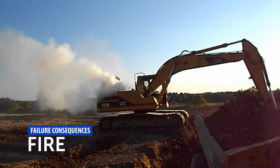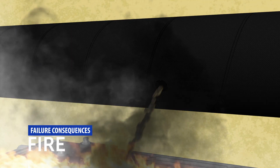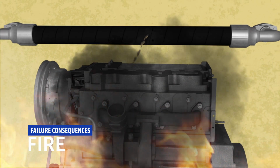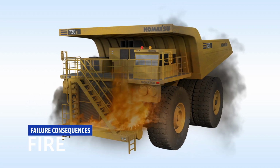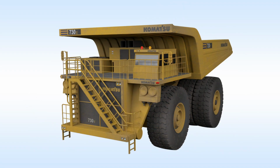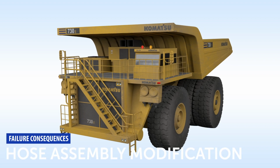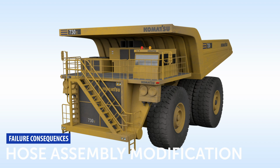Fire. Fires can start from hydraulic leaks that a human eye can barely see. As seen here, the hydraulic hose has a pinhole leak and is leaking onto a hot engine, resulting in a plant fire. There is a significant hazard not only to personal safety, but to the entire business. The hazard can be easily reduced by the inclusion of hydraulic hose diffusion abrasion sleeving. This time, the hose is seen fitted with a DAS or diffusion abrasion sleeve containing the leaking fluid, in turn reducing the likelihood of a fire occurring.